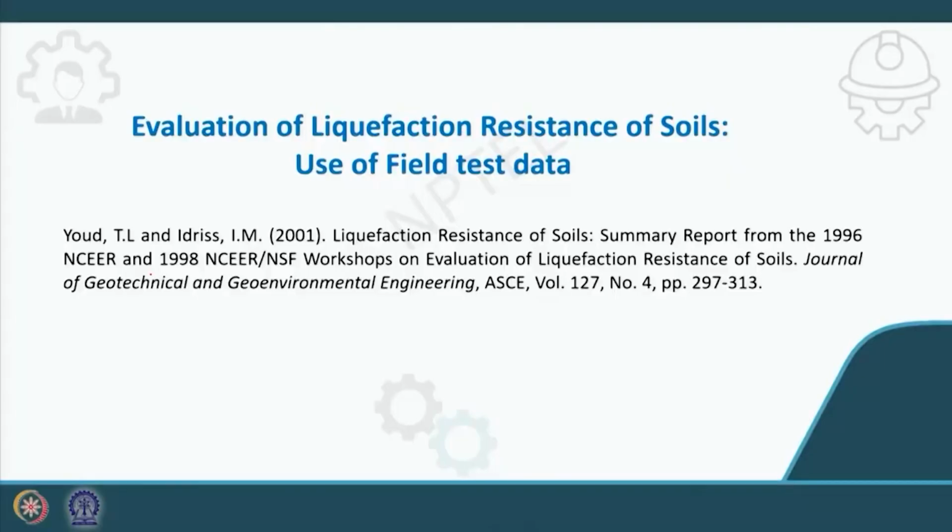There are different test methodologies available, whether field or lab, but as you now know, field test methodology is more preferable and recommended over the lab methods to check whether liquefaction will occur or not. For evaluation of liquefaction resistance of soil, the field method is more recommended.